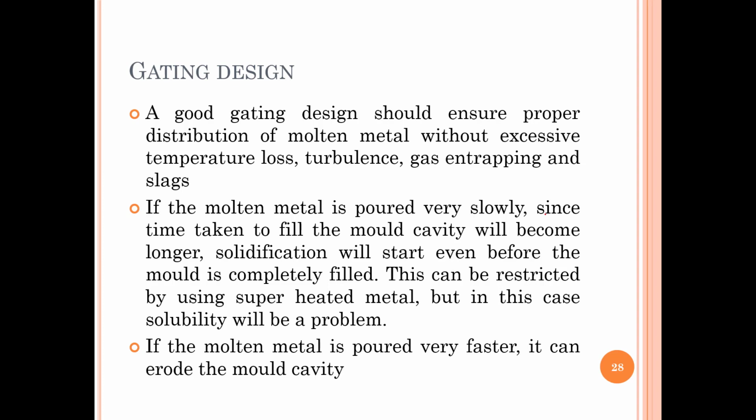If the molten metal is poured very slowly, since the time taken to fill the mold cavity will be longer, solidification will start even before the mold is completely filled. This can be restricted by using superheated metal, but in this case, solubility will be a problem. If the molten metal is poured very fast, it can erode the mold cavity. So in both cases we have some problems.